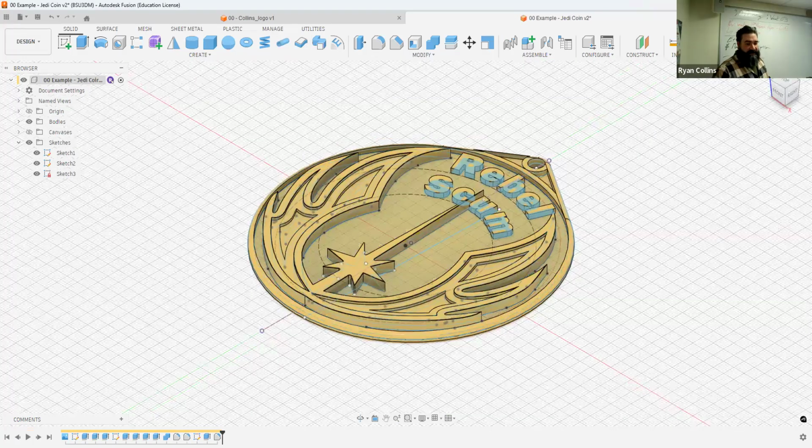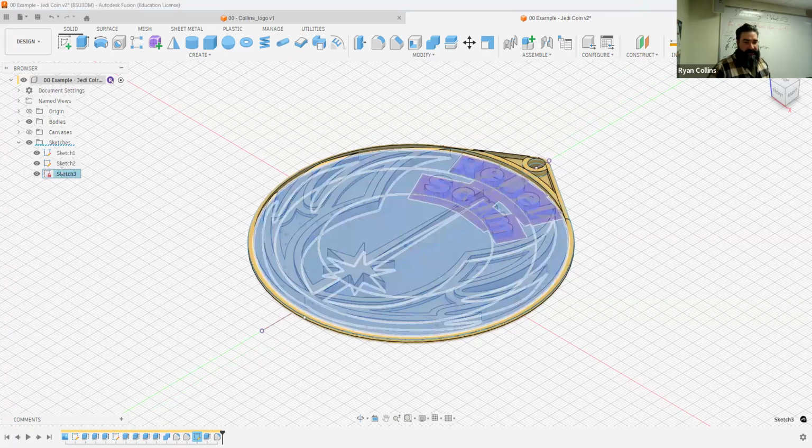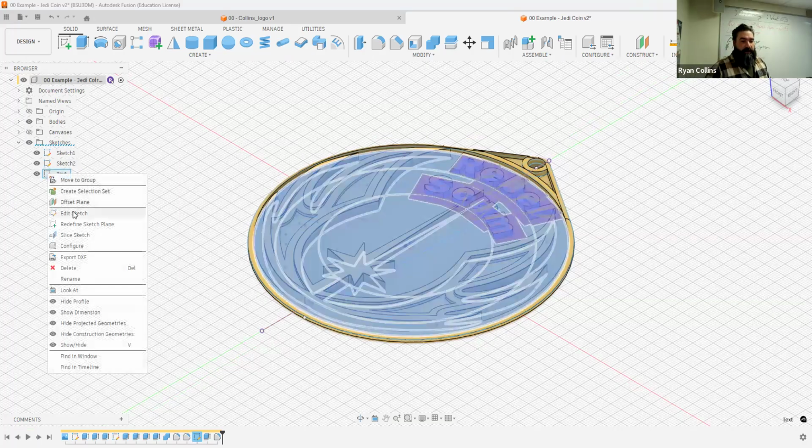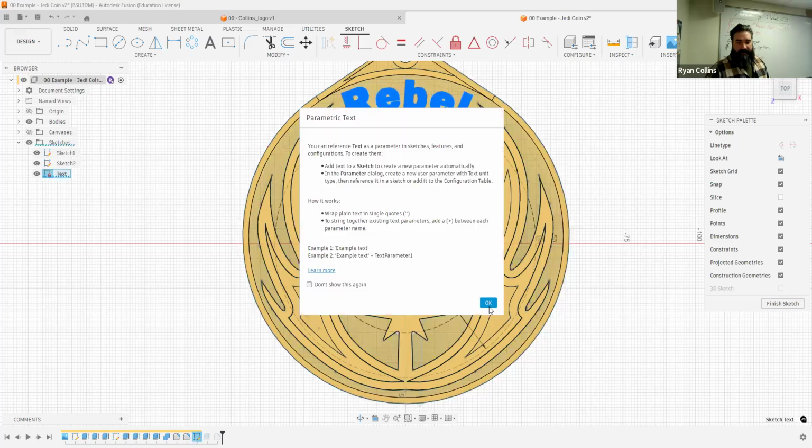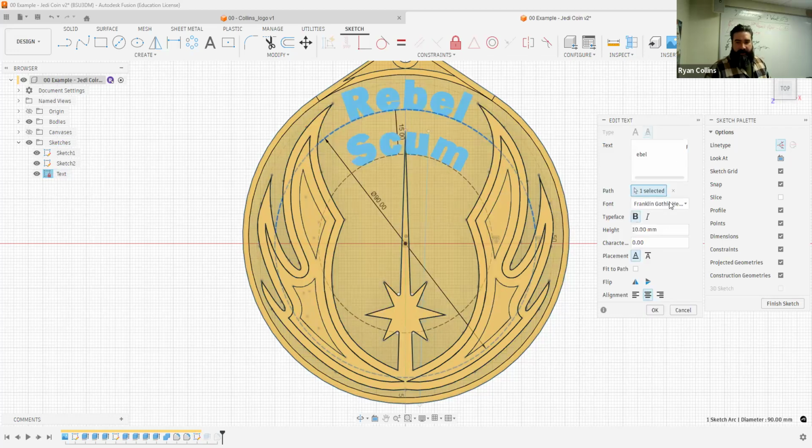So if I'd gone in and, let's say, which one has my label? There we go. Which I should have written in here. Text. Always label your stuff. Edit sketch. So if I wanted to, say, double click in here, yep, parametric text, great. It's going to come back in. And let's say I wanted to use a different font or a different size, anything like that. Doesn't matter. Let's bump that down to like 8. Of course, that's going to mess everything up. Whatever.